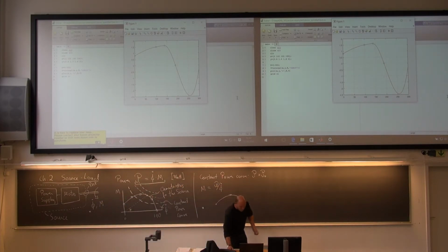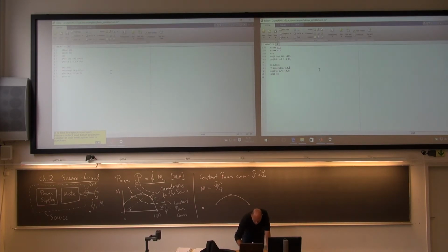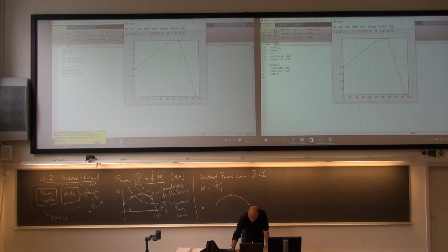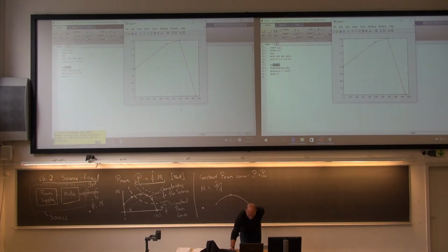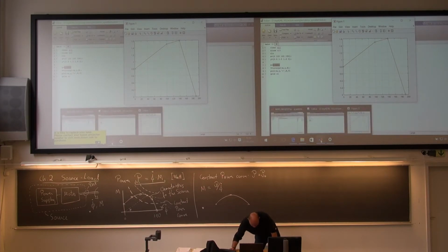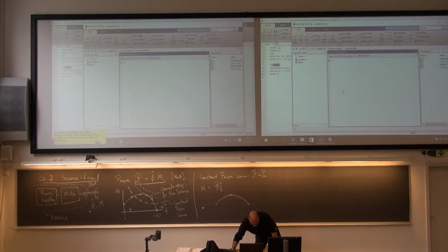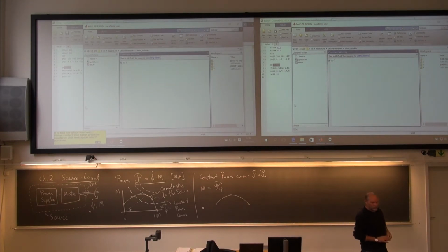If you take the linear default interpolation, you see he refuses to go outside. Although here I have asked him to plot all the way up to 300, but he refuses to do so when it's linear. He stops at 190. So I'm not sure even if he gives a warning. Let's see. No, you get no warning. He just skips if you try to go outside, if you try to extrapolate.